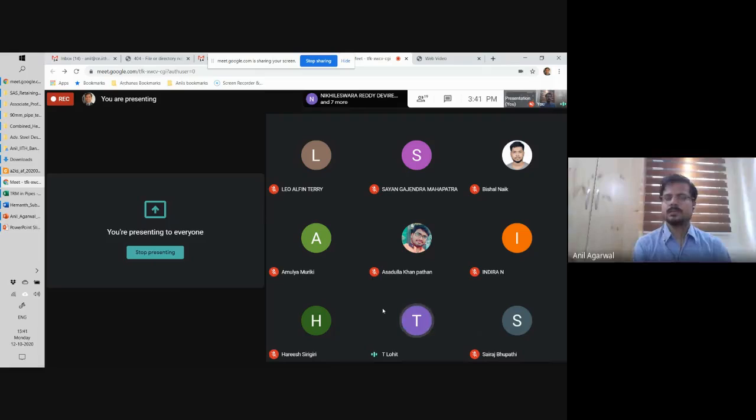Very good. Yes, exactly. That's what is required. So basically, just to reiterate, first you look at the building, how tall the building is and what is the use of the building. With these two pieces of information, you decide what type of fire resistance is required. That is called fire resistance rating. Those tables are all given in NBC part 4.